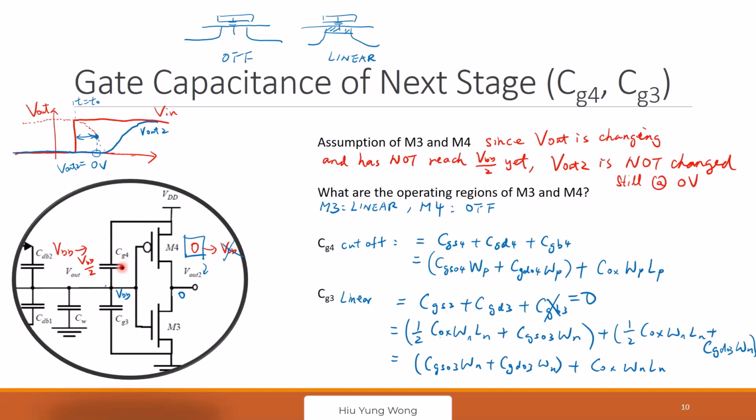That's basically because of the routing. Because now we want to find the delay, we want to see how much capacitive loading it presents to the first stage. Good question, ask why we do something. You need to charge up the wire, and also charge up the next stage so that this one can flip, so your signal can propagate to the next inverter. Okay, so now